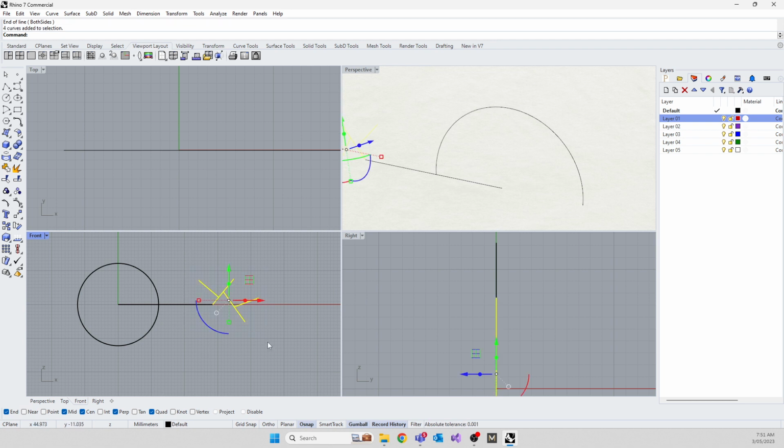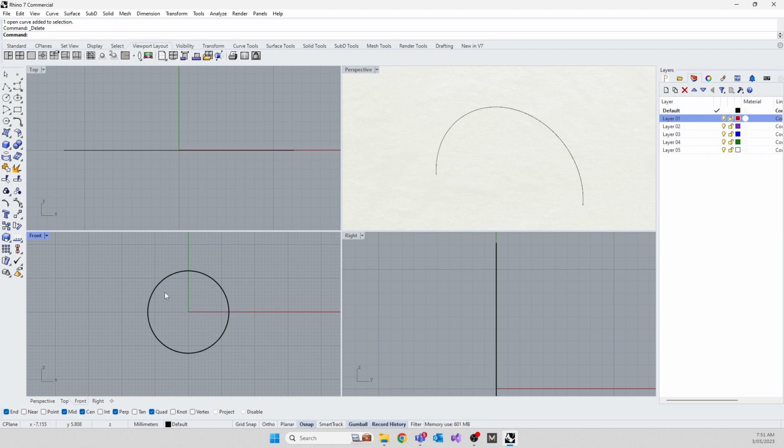I'm going to get there in a second. So the quad O-snap, think of it like a compass. You've got quadrants of a circle. You have a north, a south, an east, and a west. Or you have a 0 degree, a 90 degree, a 180 degree, and a 270 degree. They live here. Now for jewelry, this is important because you have bottom of the ring, top of the ring, left-hand side of the ring, right-hand side of the ring.